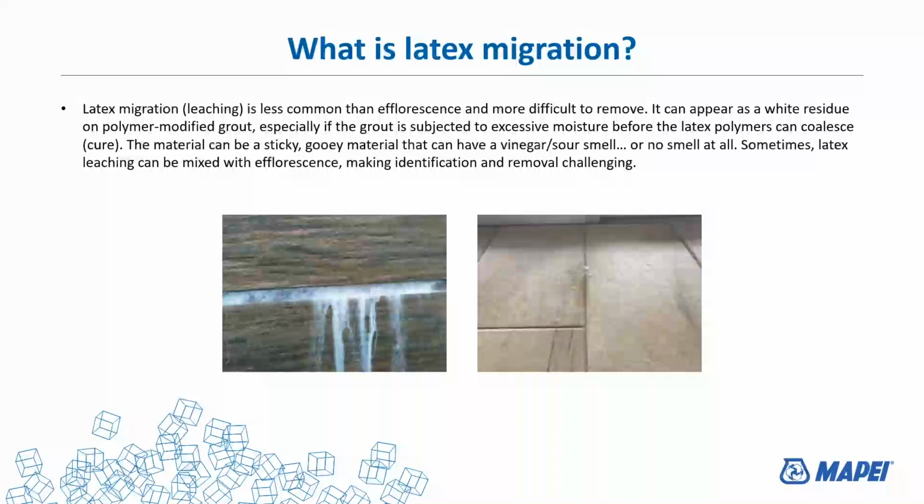Sometimes the latex can be mixed with the efflorescence, making it come out together. And if that is the situation, it makes it harder to identify, which makes it a little bit more of a challenge to remove, because now we've got latex and minerals, and what might work on one doesn't necessarily work on the other.